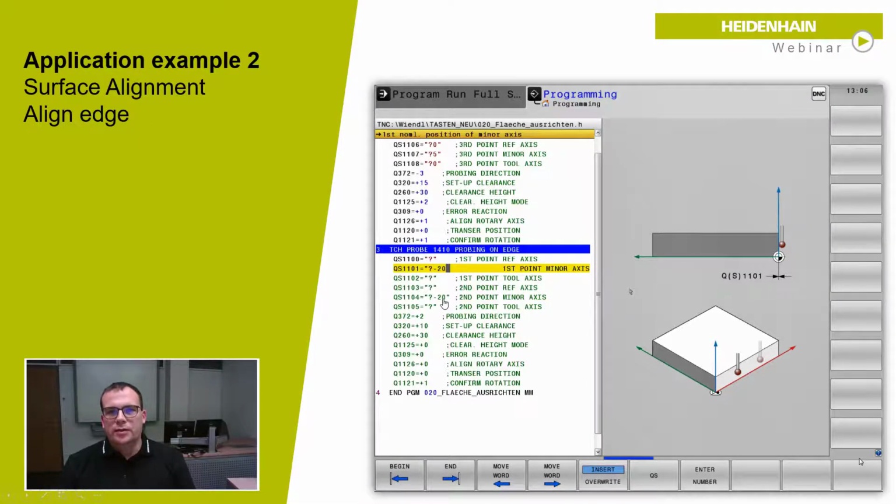can calculate. When I only program a question mark without any value, the control takes automatically the actual position as nominal position. And then we can calculate the correct angle, or prepared angle for my probing situation. So this is also a possibility that I only input a value in the probing direction, and the rest I just let empty without any entry, just a question mark in it.